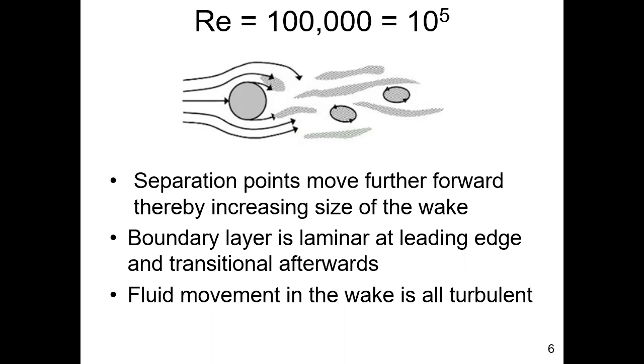In the leading edge, we're converting p over gamma to v squared over 2g, which is actually fairly efficient. As we go into the trailing edge, we're now reconverting back. We're going from v squared over 2g to p over gamma, and that's not as efficient. And so what happens is the flow field geometry is changing faster, expanding faster than this conversion from v squared over 2g to p over gamma can happen. And therefore, the boundary layer strips off of the solid object at a location we call the point of separation and goes off into the fluid as this intense zone of shear. And that's what separates the wake from the rest of the fluid.